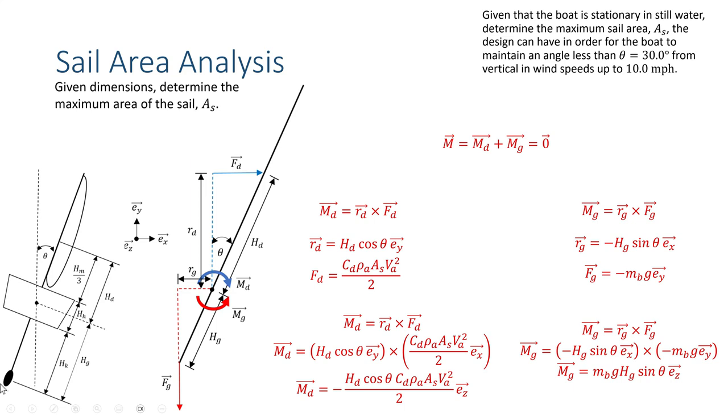So if your ballast is all the way touching, then you've got that distance from the bottom of the ballast to the top of the ballast. And then you have the keel itself. And then you have about a third of the hull, but what if your calculations are a little bit off? So maybe it's closer to half of your hull is down in the water. But this distance here, your keel height, is a variable that you have. And so you can get away with a little bit less weight if you have a little bit longer keel.